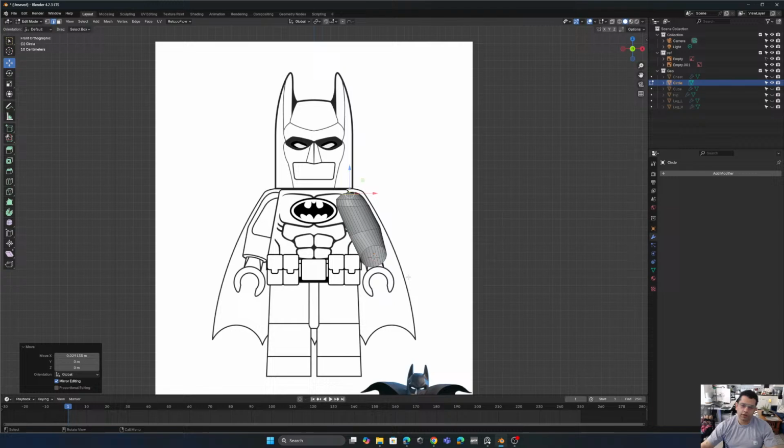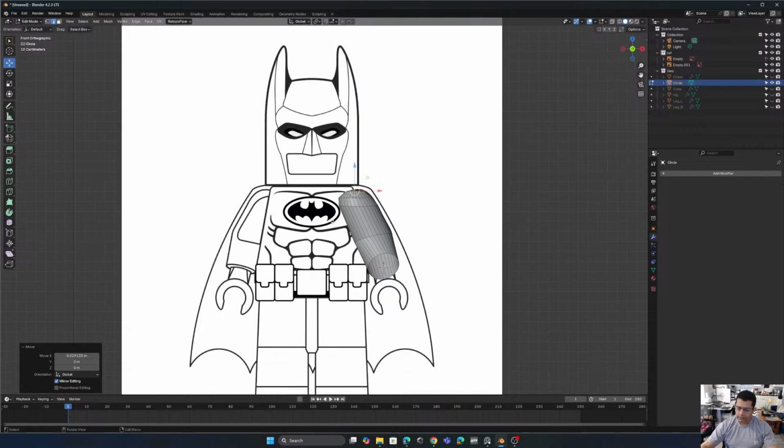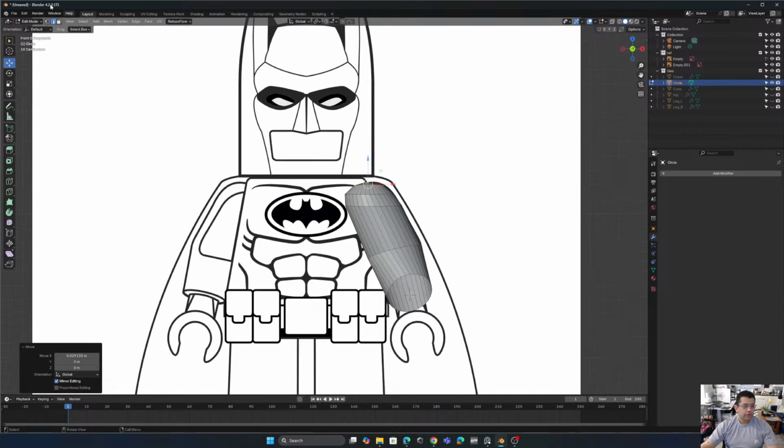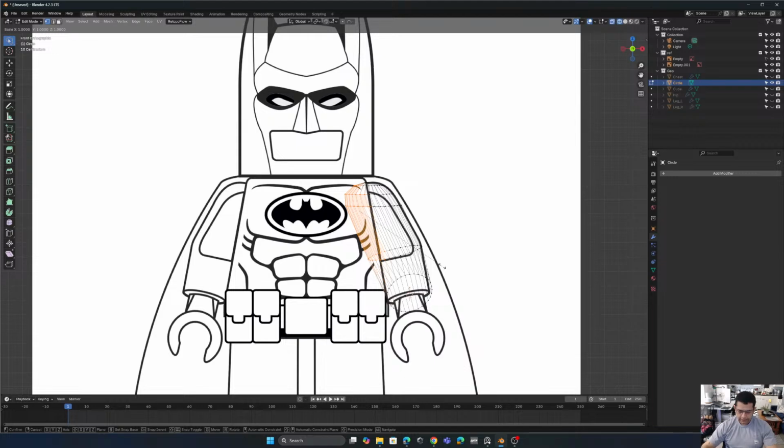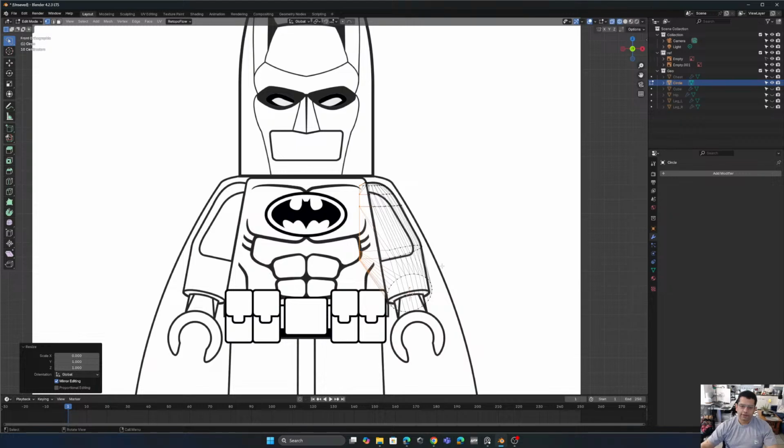So we're gonna go to front mode, pressing 1 on the Num keypad. We're gonna go to vertices mode. We're gonna select with the lasso. We're gonna select all, Shift Z to make transparency mode, and we could select the back too. All this, S to scale it, X to select the axis, and 0. Now we have a flat shape, and we could move it.